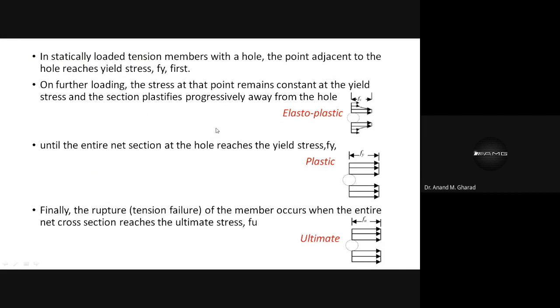And based on our earlier assumption, if you remember, what we do, we convert that non-linear part into linear part, okay, in order to simplify the things, right? And because of which you can see over here or over here, the linear variation is observed. Or in other terms, this variation of the stress has entered into the plastic zone, and therefore we call it as the elastoplastic zone. And this elastoplastic zone is observed when we increase the amount of pull.